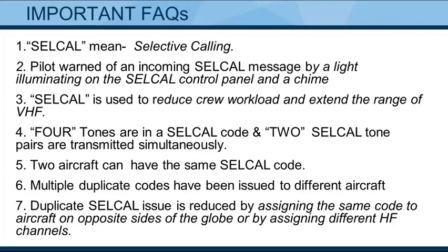2 aircraft can have the same Selcal code. Multiple duplicate codes have been issued to different aircraft. The duplicate Selcal issue is reduced by assigning the same code to aircraft on opposite sides of the globe or by assigning different HF channels.